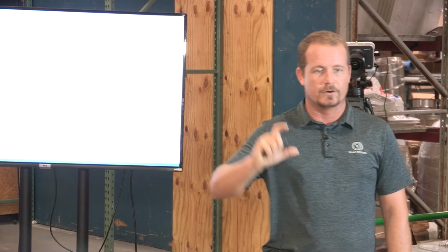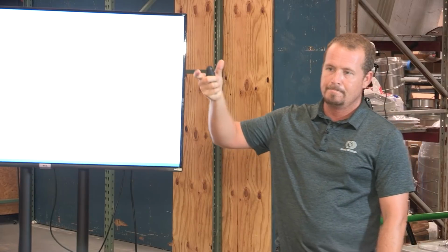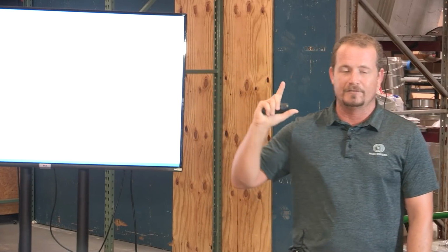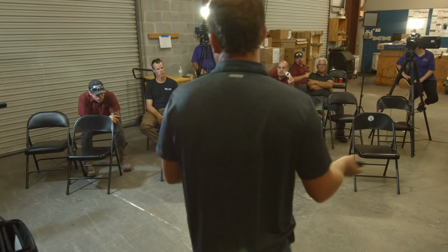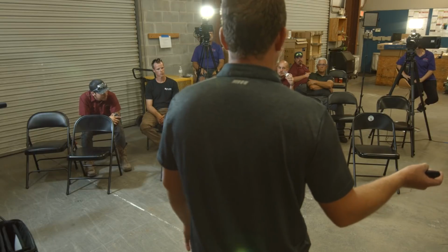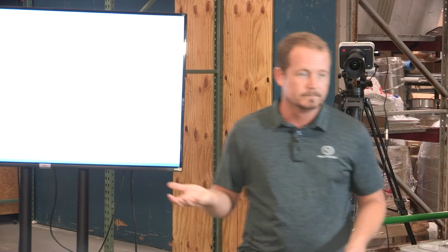Now, quick question. Under what condition do you have to measure voltage in order for voltage drop to mean anything? Full load, right? The thing has to be running full tilt. So if you have a system that has highly variable load in it, like sometimes it's under much more load than others, you have to make sure that you're at maximum load. If it's a multi-stage unit, that means it's got to be at high stage.